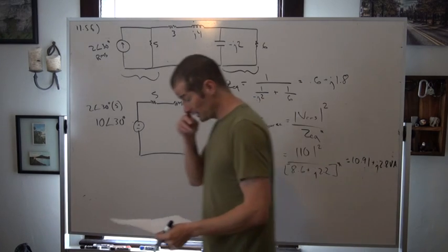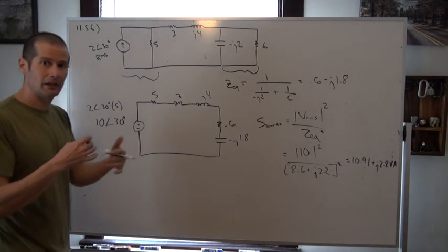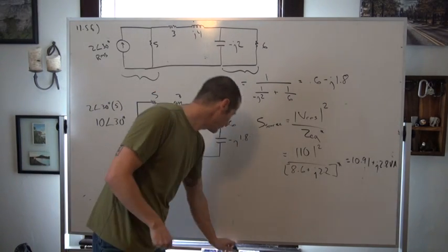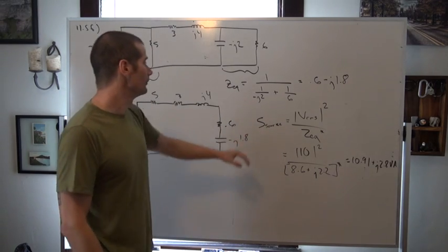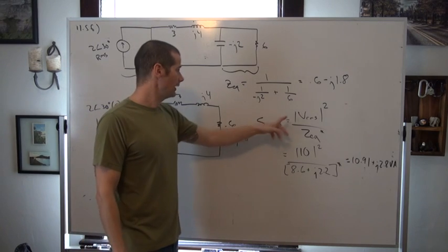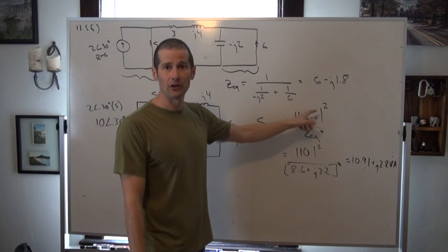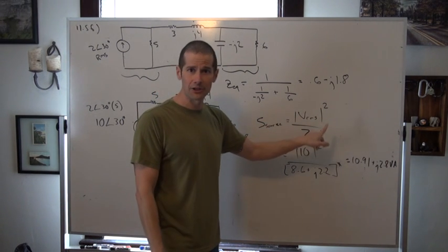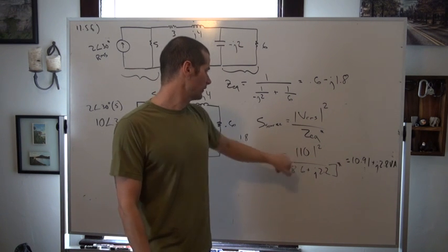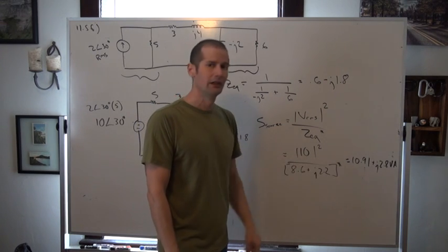volt amperes. So let's talk about the impedance a little bit and a correlation to the current. Now, this is fantastic here, because here we see the other variation once again. We've seen this in another video of basically how we can easily just calculate that complex power. In this case, VRMS squared over ZEQ conjugate, which is equal to the magnitude squared over 8.6 plus j2.2 conjugate.